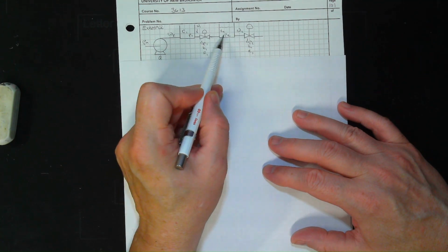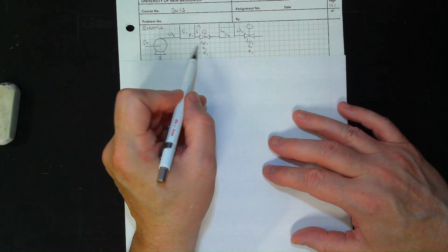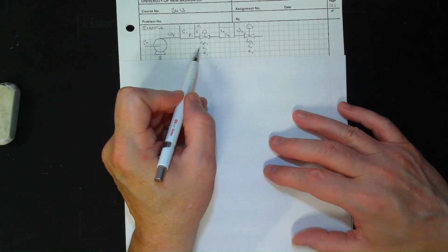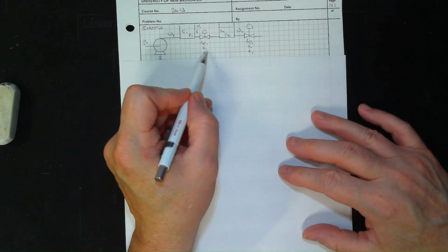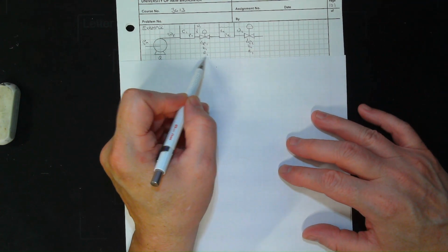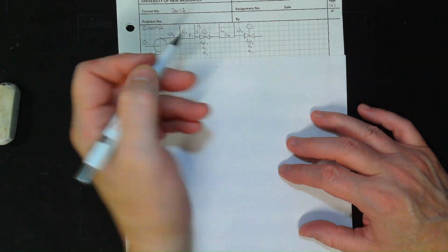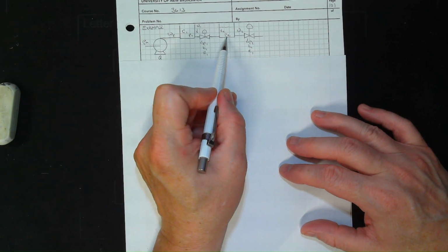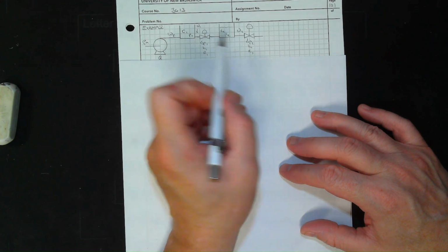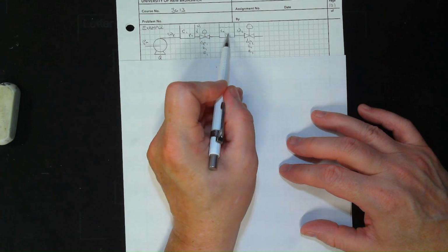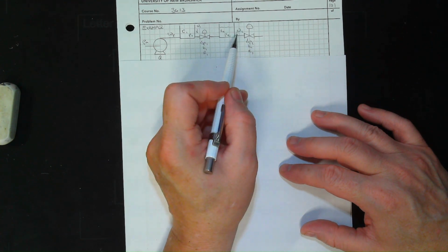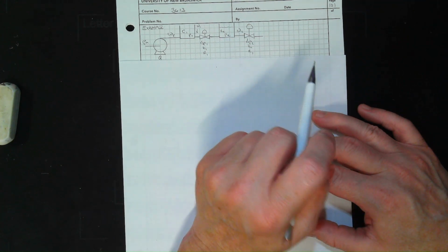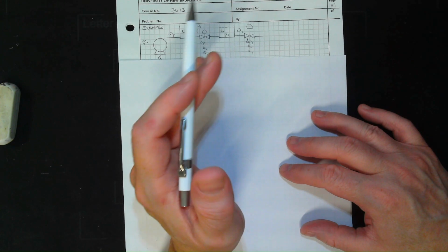Then we go through this valve, which has a pump characteristic. We'll just call it R1. It has K1, but that produces R1 when we linearize it. And so we're going to go from P1 pressure drop down to P2. Then some can get stored here. So that creates omega 2 here, which goes to a valve that is just jumping out, dropping down onto ground, atmosphere, to a pond, what have you.